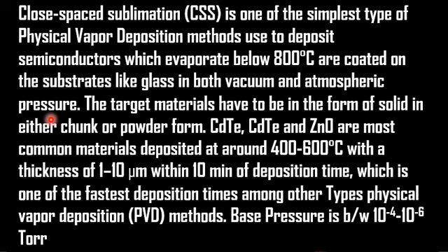Now what do you think? What is the reason why the film prepared at low vacuum pressure has less impurity compared to the film prepared at high pressure? Just please note that when a low vacuum is created in the reaction chamber, the mean free path for the evaporated material from the precursor increases beyond the distance between the precursor material and substrate material.